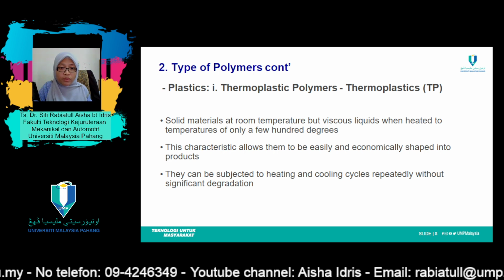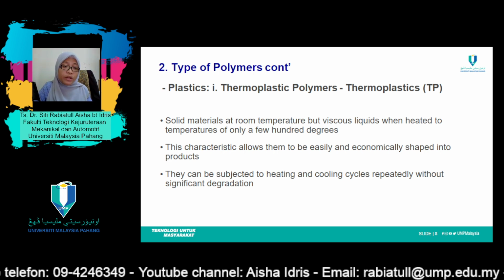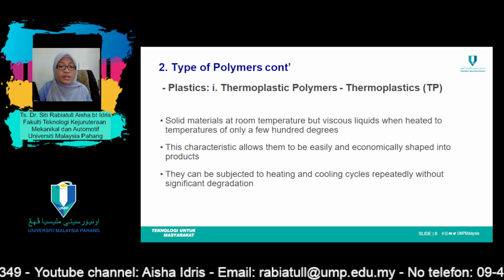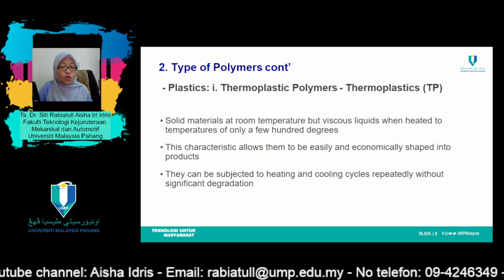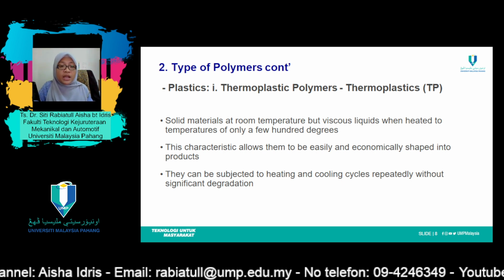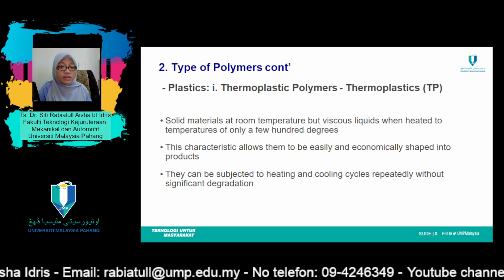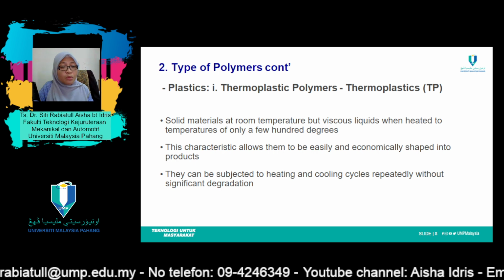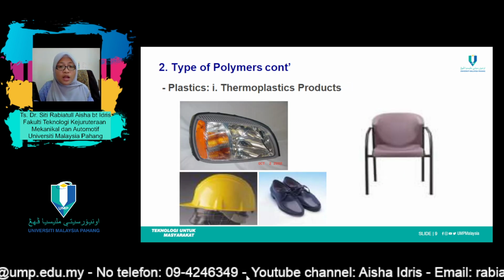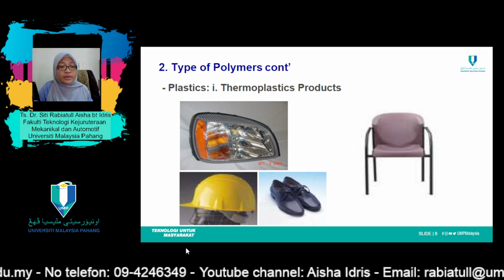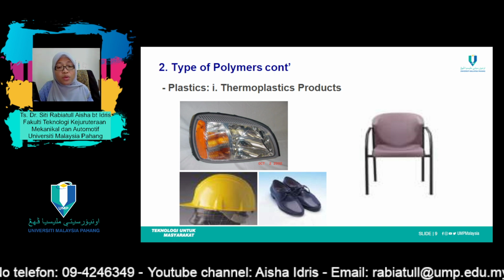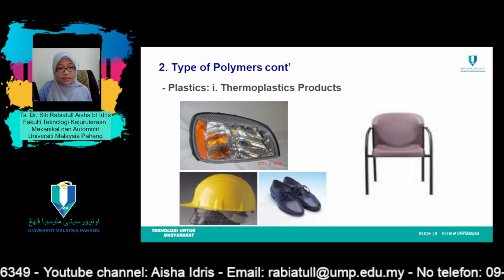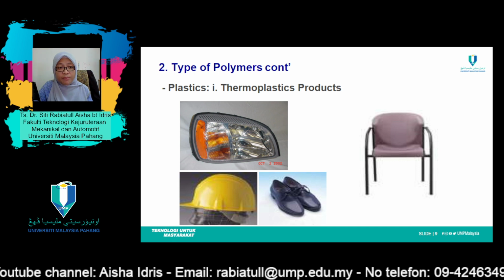On a molecular level, as the temperature is raised, secondary bonding forces are diminished so that the relative movement of adjacent chains is facilitated when a stress is applied. Irreversible degradation results when a molten thermoplastic polymer is raised to a high temperature. In addition, thermoplastics are relatively soft. Most linear polymers and those having some branched structures with flexible chains are thermoplastic as well. These plastics are normally fabricated by simultaneous application of heat and pressure.